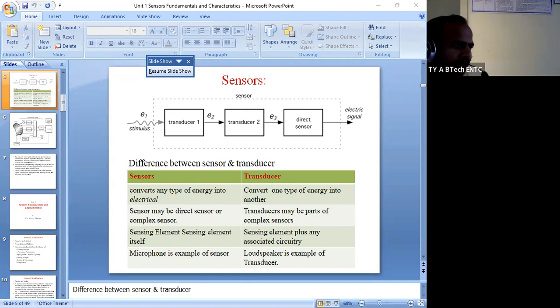Some standard rating is there. For a two-wheeler, 30, 40 is the front and rear combination; for a four-wheeler it is different, and for a truck again different. According to the requirement and dimension of a tire, the standard air pressure to be maintained is mentioned. In showrooms or garages they mention the minimum and maximum, front and rear, for two-wheelers, four-wheelers, heavy vehicles, containers and trucks. Air is the same, but the pressure maintained in each tire differs.